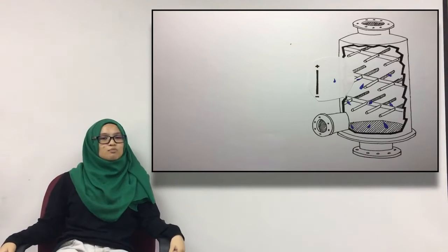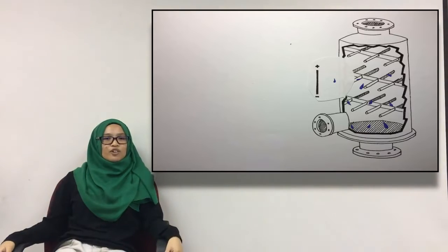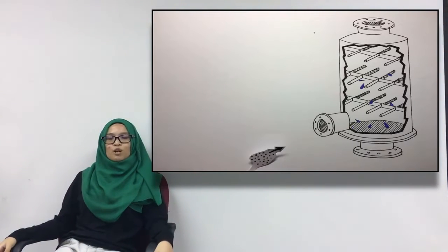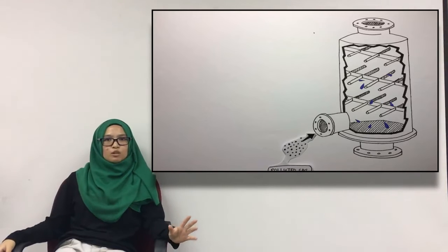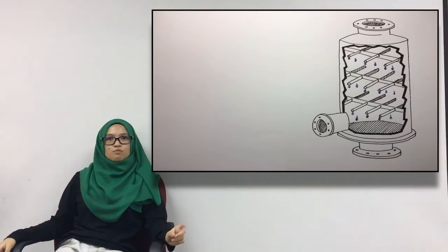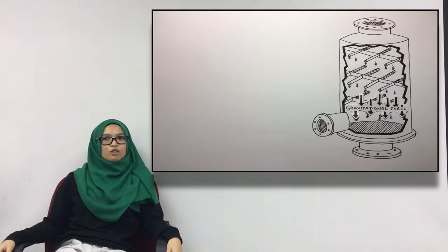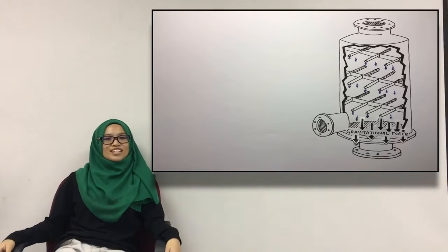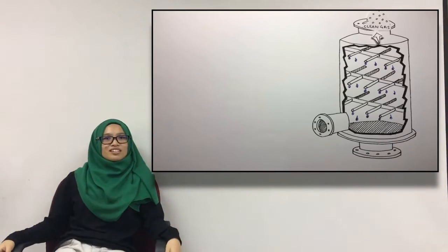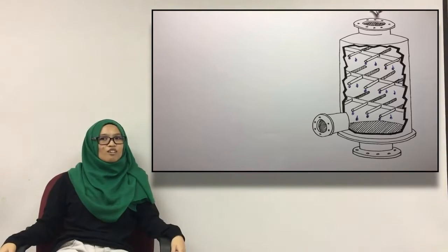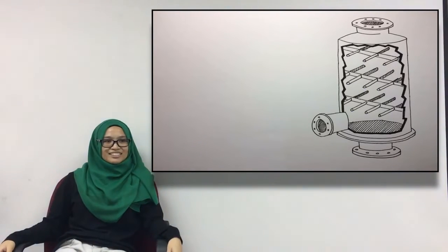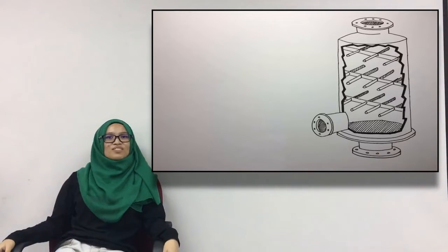The spray chamber can also be oriented as cross flow and concurrent flow. Polluted gas contacts the scrubbing liquid, and water sprays downward from nozzles mounted on the walls of the tower or mounted at the center of the chamber.